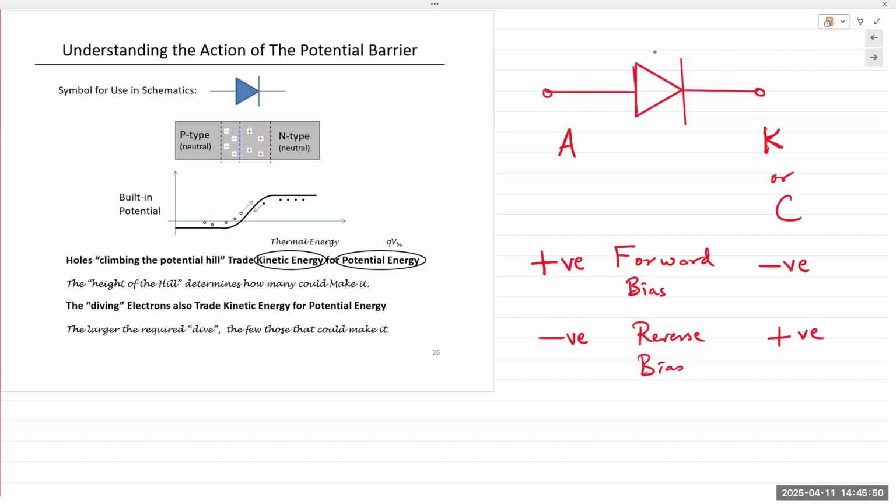Okay. So going from the N side to the P side, of course, the electric field is in this direction, right? It's higher on the N side, lower on the P side, in that direction. Holes are on the P side. They have to climb, overcome the barrier, and go on the other side. Electrons must cross the junction, meaning they have to let go of some of the energy, but they also must be pushed towards the P side of the junction. Okay. In both cases, they are moving against the electric field in a sense.